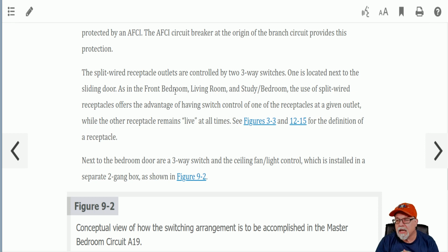Doesn't care. Now, in commercial applications, there have been some arguments. Let's say I'm using it in a commercial environment where I have metal cover plates, and those metal cover plates come loose and I have something plugged into it. If you have the grounds down, then that metal cover plate could slide off and slide down and cause a short, if there's a gap between the attachment plug and the actual receptacle outlet, and that would actually trip a breaker.